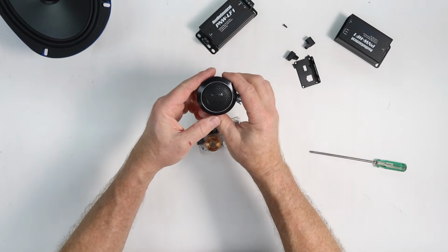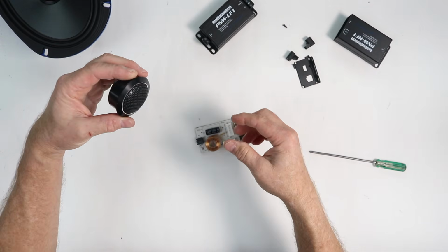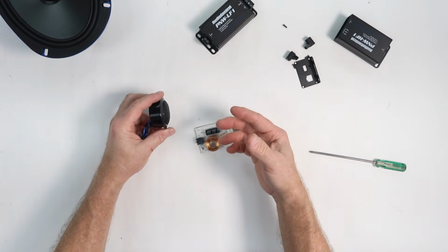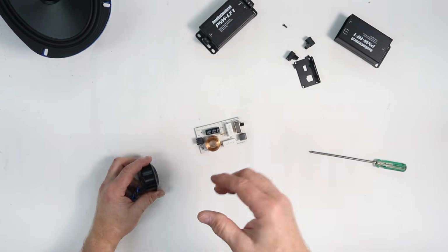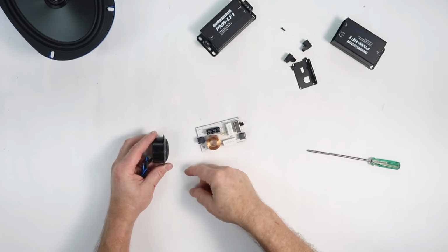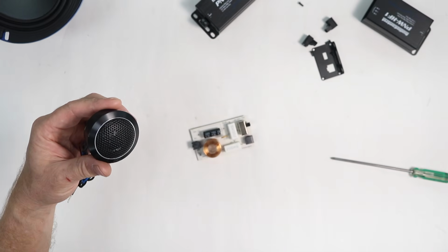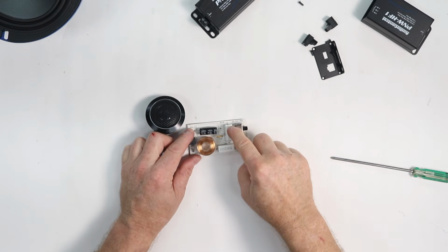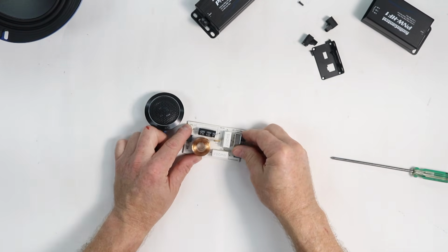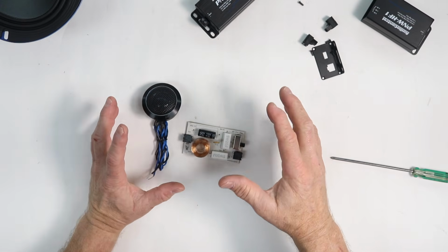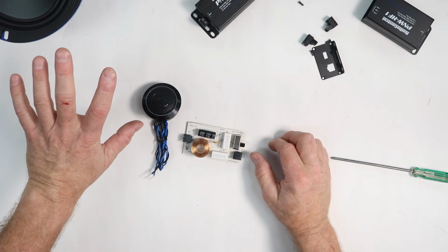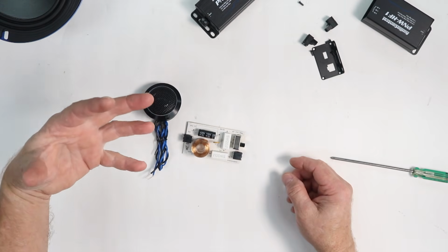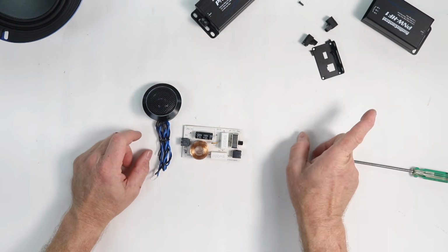When we move those tweeters up into the dash, on the A-pillar, on the sail panel, or just in our face, they became a lot louder than way down there in the floor. They're up here now. And in some cases, that got to be kind of annoying. So adding in the tweeter attenuation, which is what these are for, is great, because now we can control it. It can also help if you have a tweeter really close here, but a tweeter really far away over there. This one is just overwhelming it. I can turn this one down and leave that one louder.